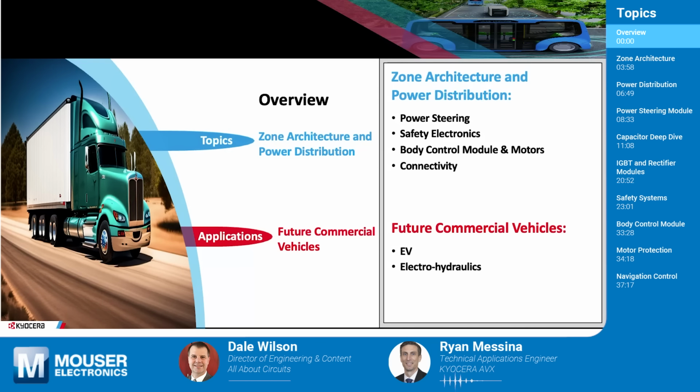You can also move power trees directly to each module. So you have dedicated power at that ECU, at that module. So everything can happen in real time, much faster. You basically create a local power supply or distribution module in each zone. Ultimately, you can make a lighter, less wiring, and therefore cheaper harness that improves fuel efficiency, handling, and performance. And then you also have processing power next to the action of a specific zone, which, like we said, allows for higher speeds and less latency.